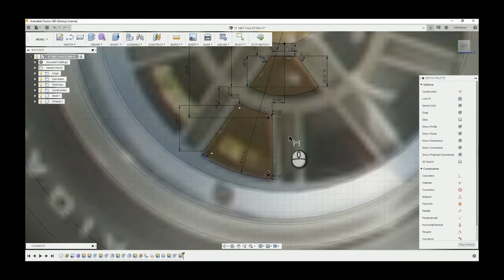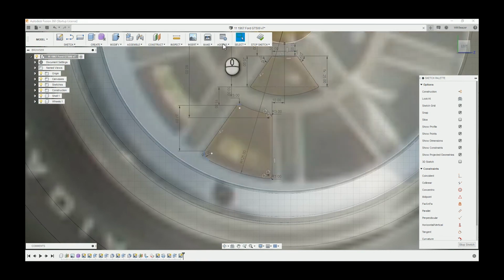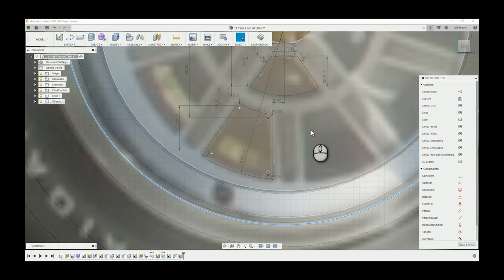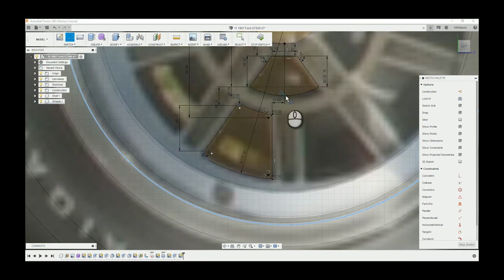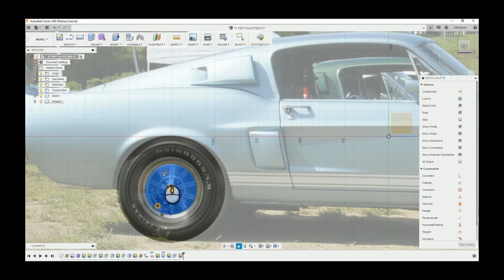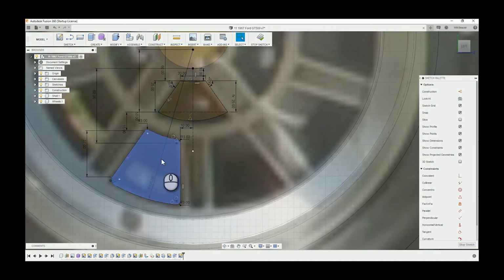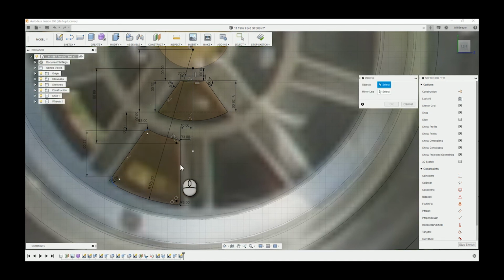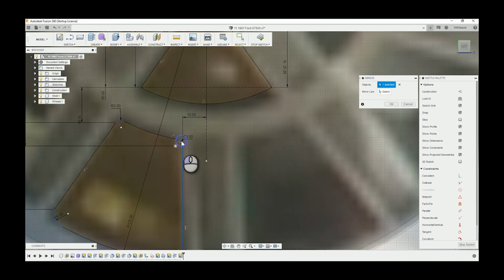And yeah, it was laziness really, but I just wanted to get on with the rest of the model. Obviously, like I said, if you're in industry, you can't do that. I did a placement for an airport seating company for about 3 months, and everything was constrained. You couldn't find any line in any of their models that wasn't fully constrained, and you can constrain them in many ways, like dimensioning, fixing points, or using constraints like perpendicular, etc. But yeah.